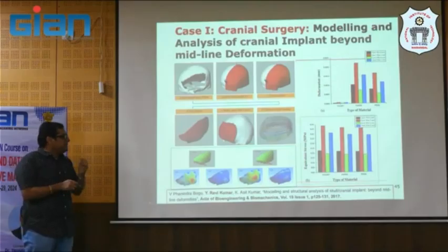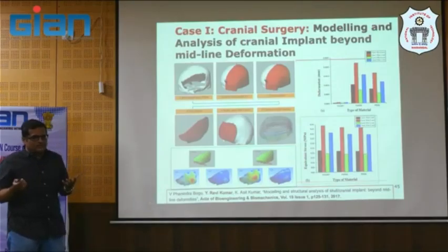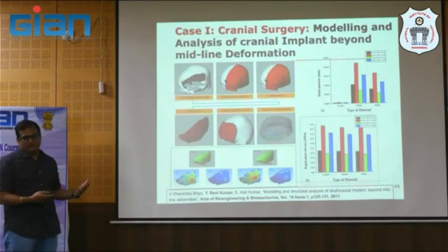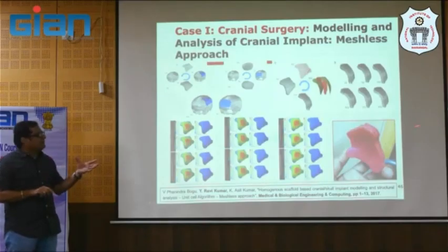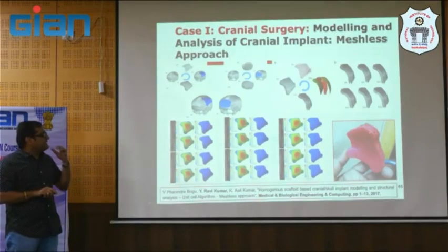Then hardly can you find a material which is biocompatible, and that too your facility must support such material, right? That is another criterion which we need to understand. And finally you design and fabricate, but here you see it is a kind of sandwich structure, your skull, right? So you have the inner thickness of the skull around 0.8, 0.9, and the outer is 0.4, 0.5, and in between you have a porous structure.